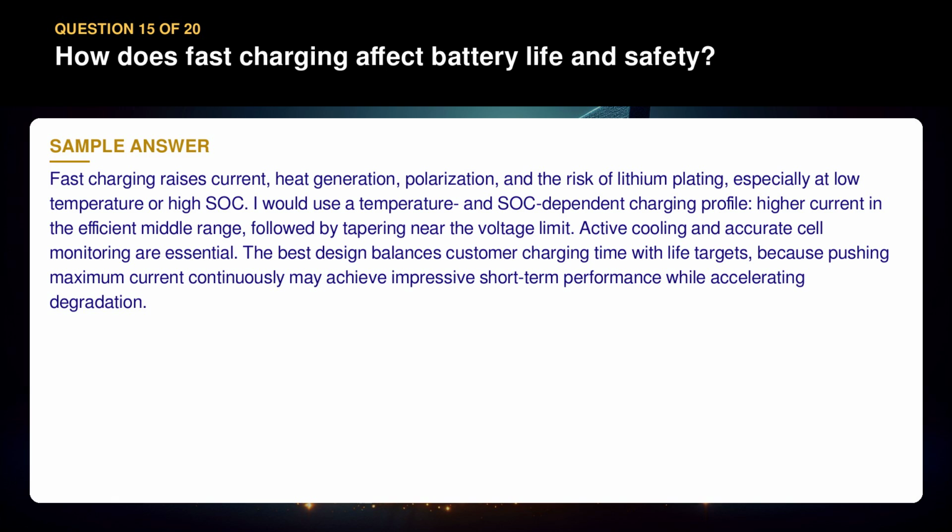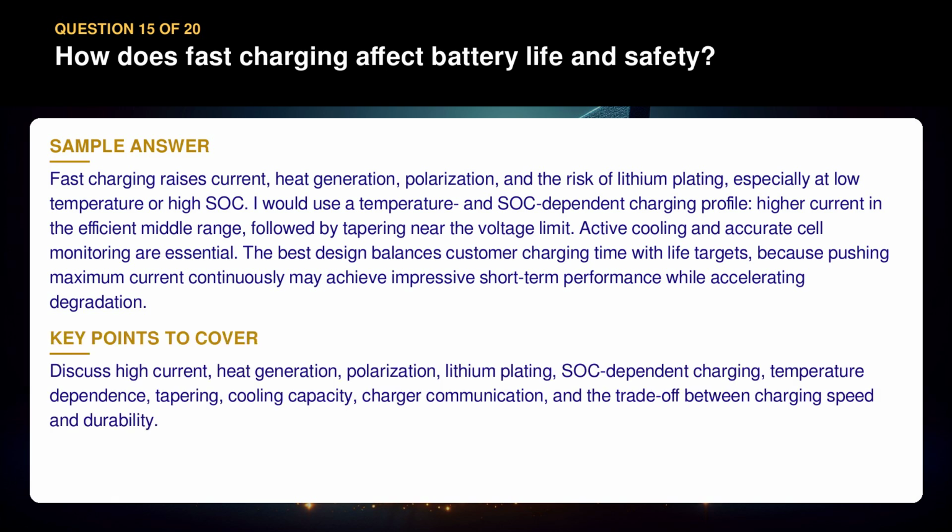The best design balances customer charging time with life targets, because pushing maximum current continuously may achieve impressive short-term performance while accelerating degradation. Discuss high current, heat generation, polarization, lithium plating, SOC-dependent charging, temperature dependence, tapering, cooling capacity, charger communication, and the trade-off between charging speed and durability.